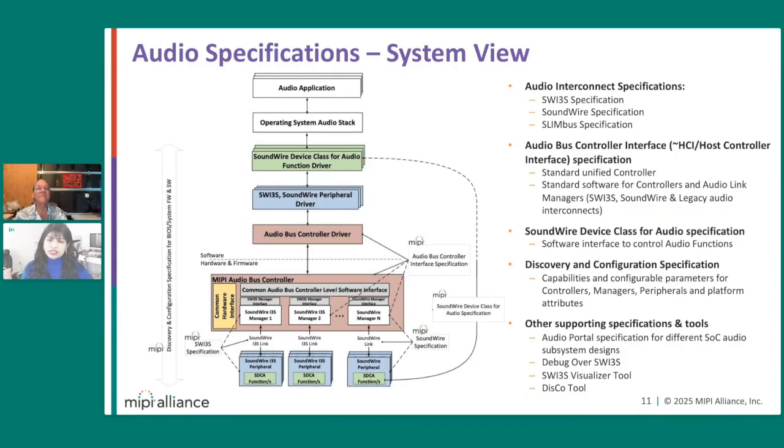And MIPI specifications are designed to support not only the hardware integration through standardized interconnect definitions, but also system integration by providing the mechanisms that can make platform details accessible to the operating system. Now, if we look at the audio interconnect itself, the MIPI Audio Working Group has been focused on addressing the limitations of legacy interconnects like I2S, TDM combined with I2C. And over time, this group has continued to evolve the audio interconnect architecture. We began with the SLIMbus specification, then advanced to the SoundWire family of definitions, and most recently, we introduced the SoundWire I3S,